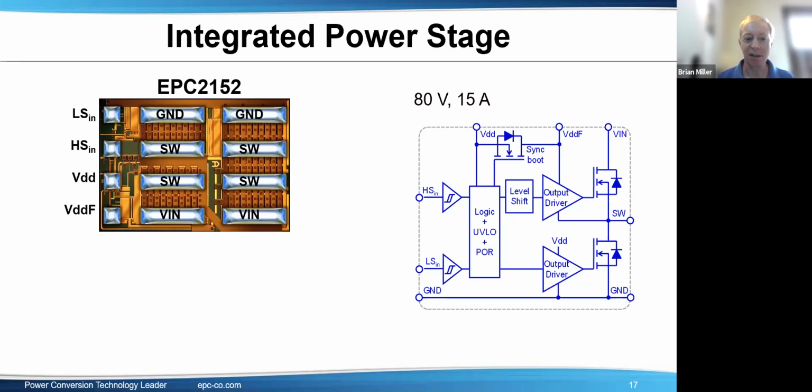Well, it depends if it's a 4-FET buck boost. You could use this. You could use 2 of them, if you have the logic signals coming in. Maybe you're asking, do you have a reference design that takes the high side from a controller with a gate driver and gets it down to ground referenced? We don't have one like that. Or a buck boost. Maybe you're asking about a SEPIC converter. We do have some SEPIC converter reference designs, but not using this part.